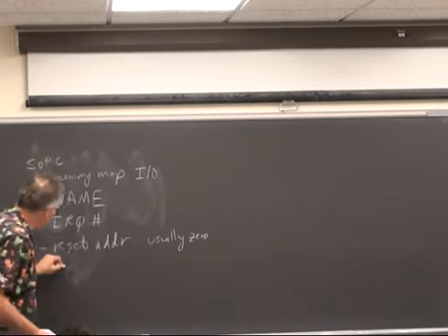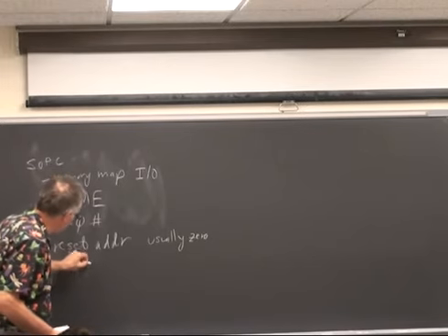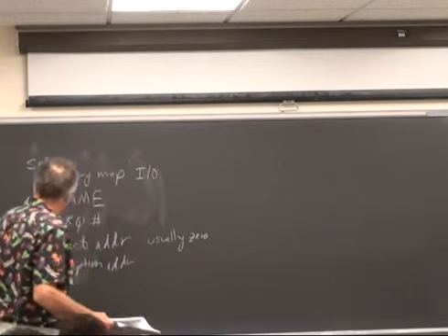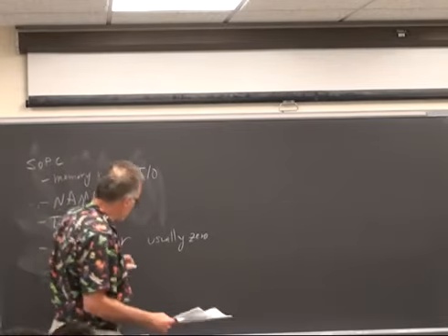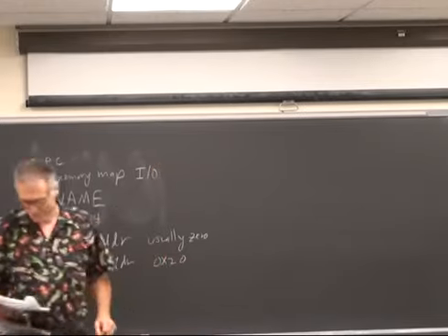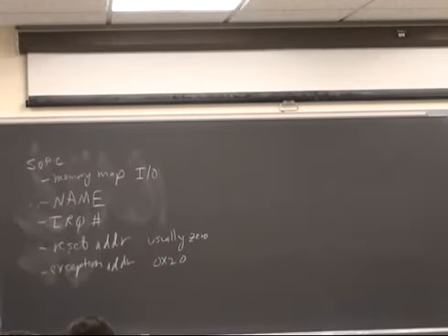You have to specify an exception vector address, and this is usually set to 0 hex 20. And every exception, hardware, software, and otherwise, goes through that same location.